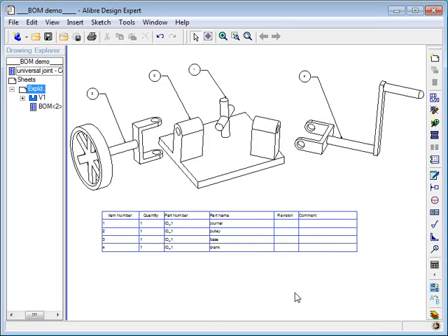As you can see, bills of material are another simple but powerful method for documenting your 3D model. Before we conclude, there's a couple of things to keep in mind. First, I need to save this drawing in order to keep the bill of materials that I created. After that, I can open it in its own workspace like the one we saw earlier. Second, a drawing file can only have one bill of materials. And finally, the term bill of materials is often shortened to its acronym, BOM.